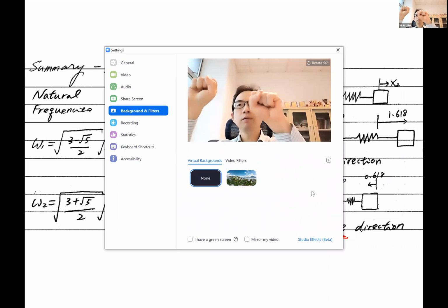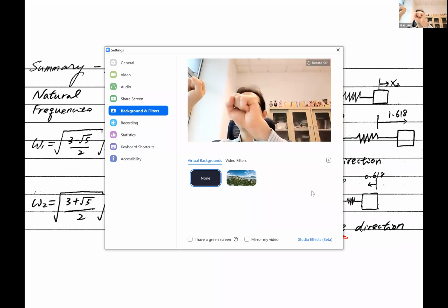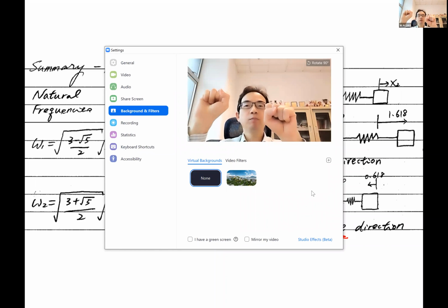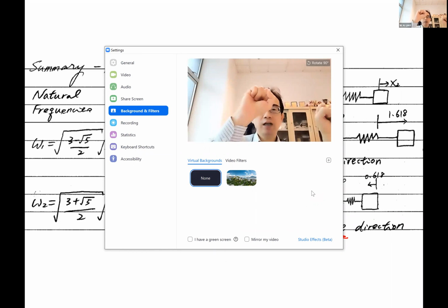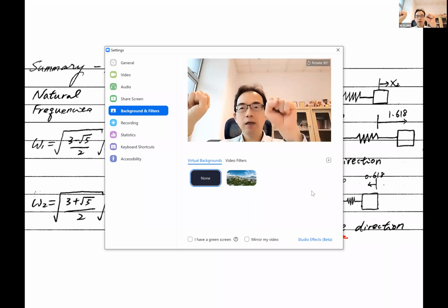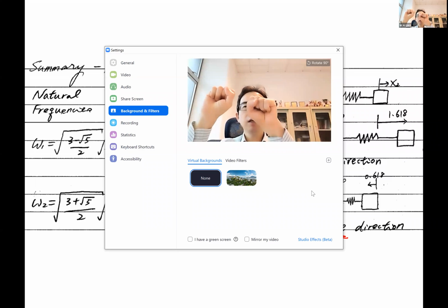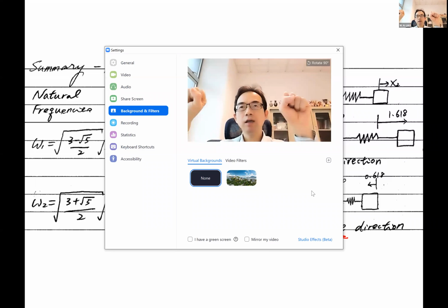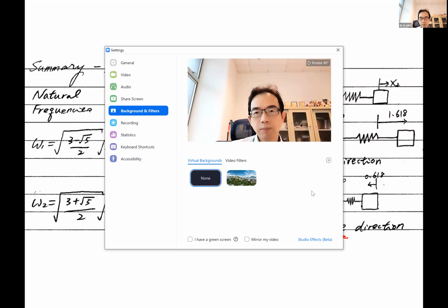So we have 2 modes. In the first mode they move in phase, I mean, like this, in the same direction. And then at omega 2, they move in opposite directions, right? One moves in this direction, and the other moves like this. Okay, something like this. Before, we only talked about a single degree of freedom, where we only had 1 mass. Now we have 2 masses, and there are different interactions between them.